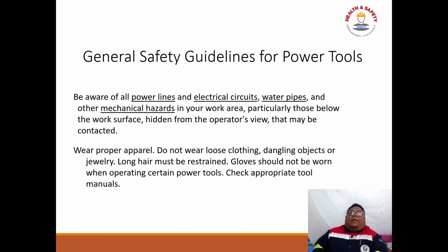General safety guidelines on power tools. Okay. Take note on this one, guys. Be aware of all power lines, electrical circuits, water pipes, and other mechanical hazards in your work area, particularly those below the work surface, hidden from the operator's view, that may be contacted.